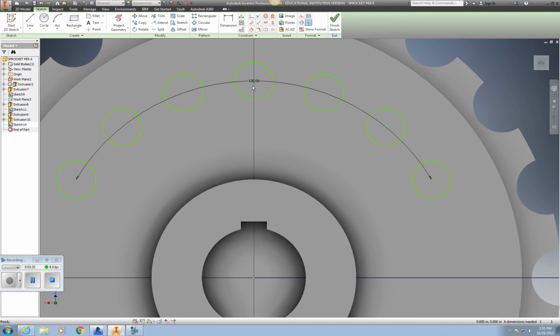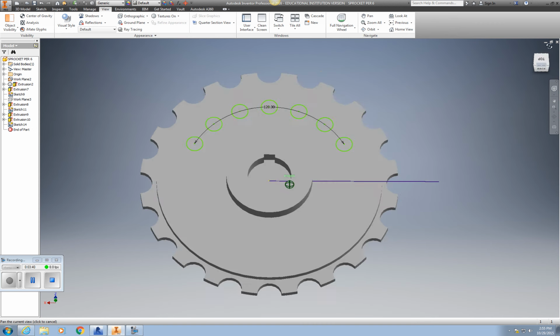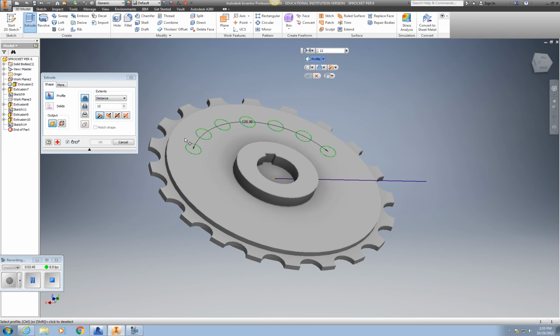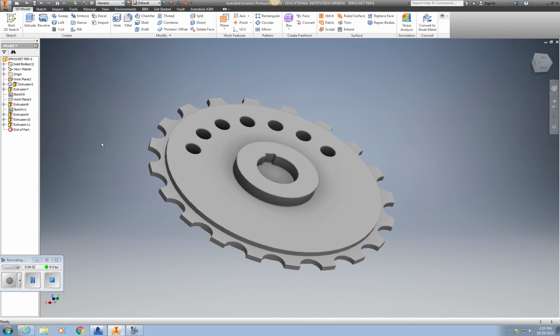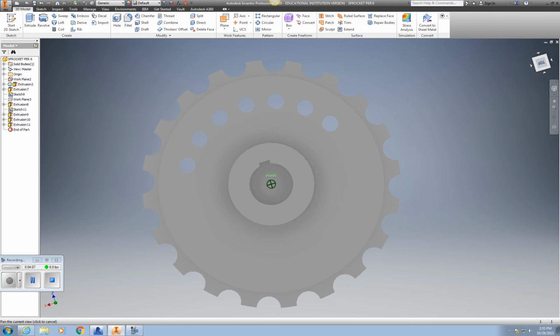So we'll pick OK. And now we can get rid of the layout line. Now take notice there's a dimension that will stay until we do our extruding. So now we're ready to finish sketch, tilt our shape on the side, and we'll go ahead and extrude under 3D. So we'll go ahead and pick every circle first, and we want those to go distance, pull down, all. We now know it's going to pass through the entire shape.